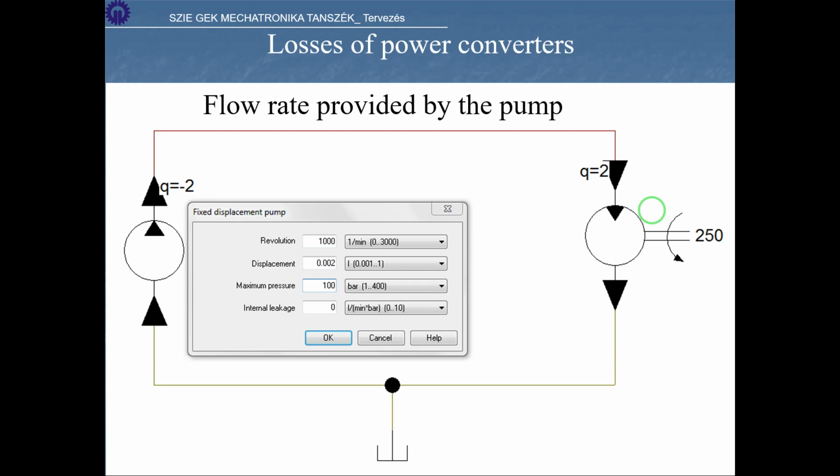And this is a real problem in hydraulics, because the hydraulic medium, which is basically some liquid, fairly usually oil, degrades at 80 centigrade, and therefore if we have a bunch of hydromechanical losses which are heating the oil, this temperature can easily be exceeded. So therefore we have to calculate this type of losses.